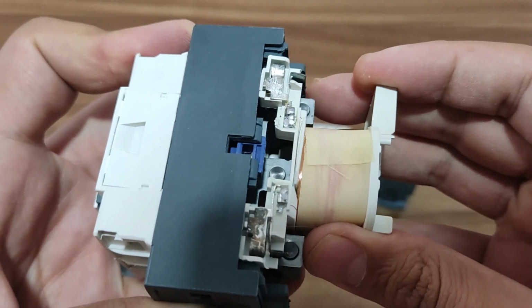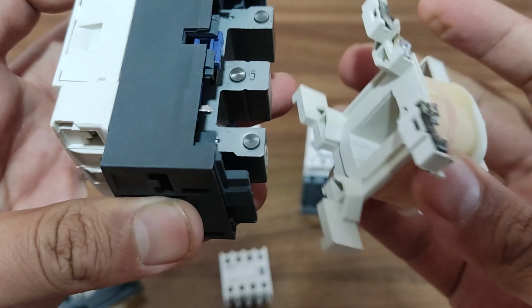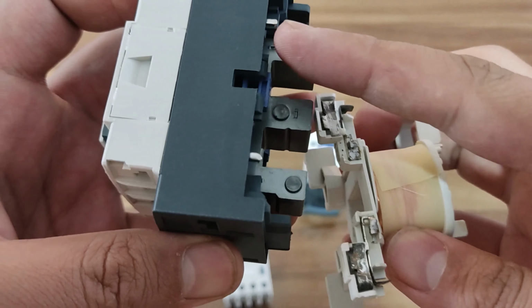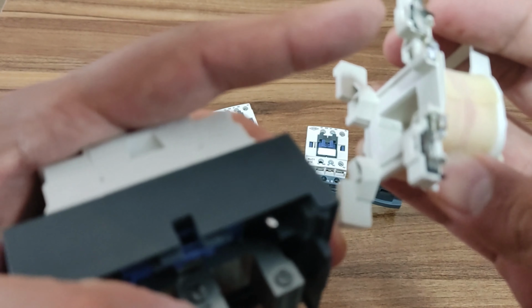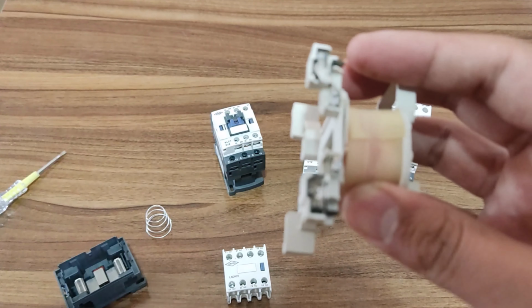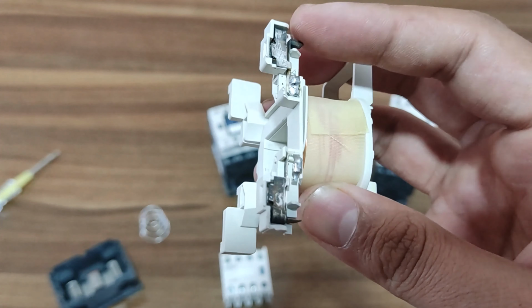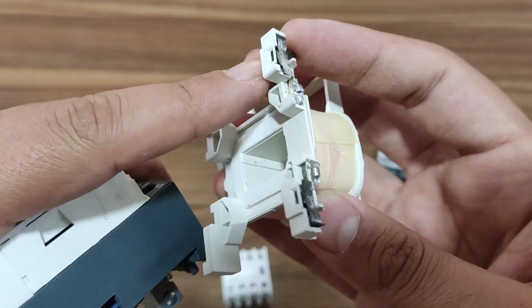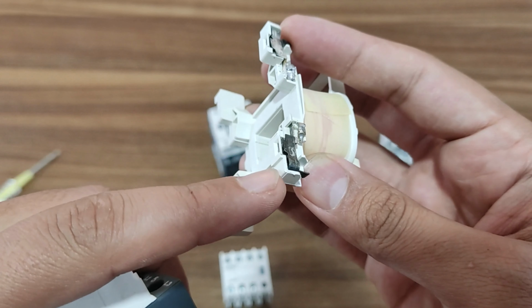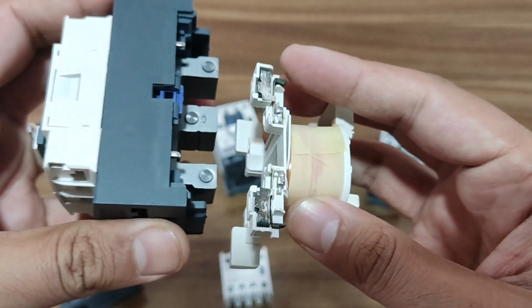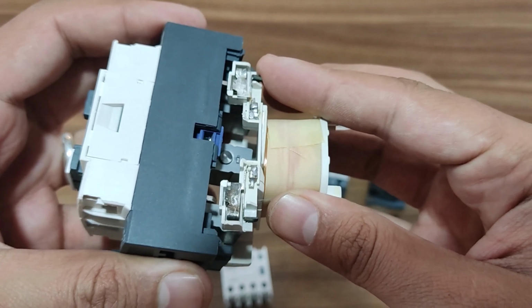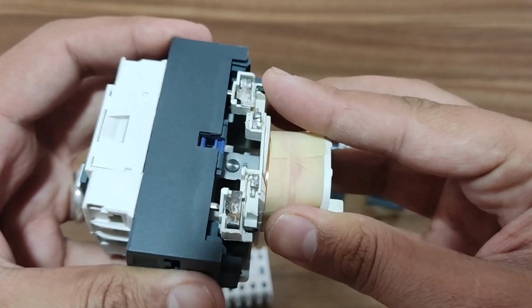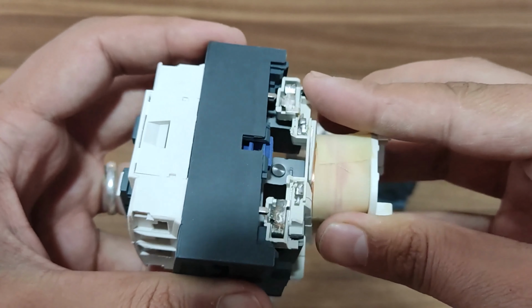In the contactors that are designed to interrupt this kind of currents, a resistance branch is used in parallel with each contact. At the moment of connection, this branch is connected first, and after controlling the current, the main contacts of the contactor are closed. After connecting the main contacts, the resistance branch is removed from the circuit. This type of contactor is used in capacitor banks that are installed in the network to improve the power factor.